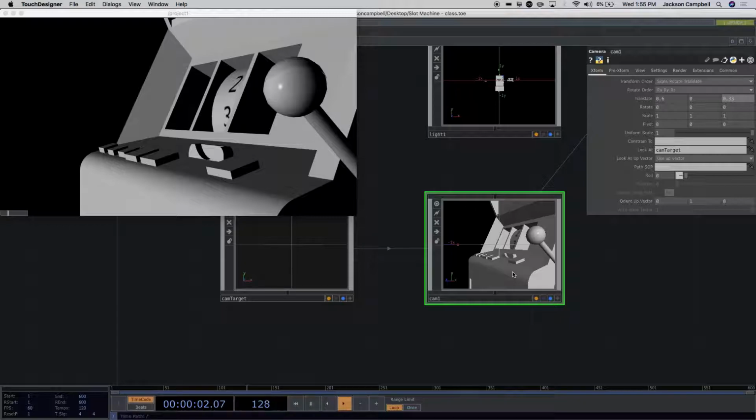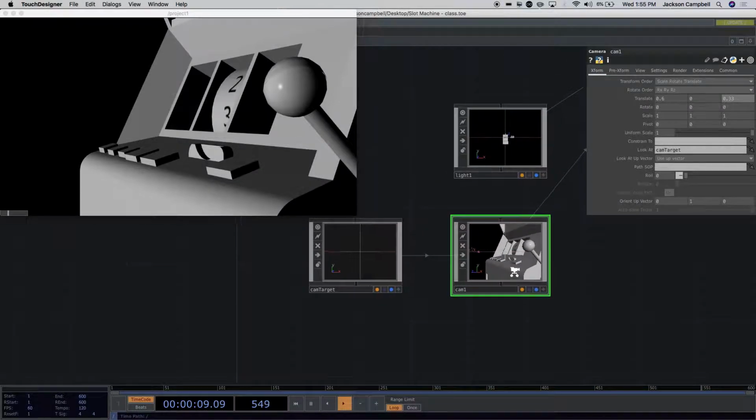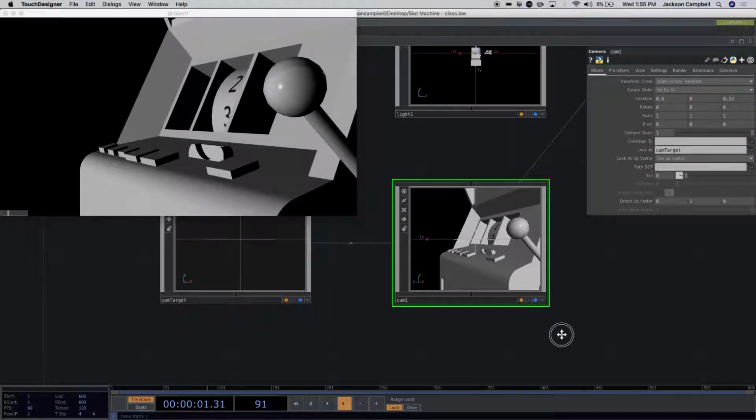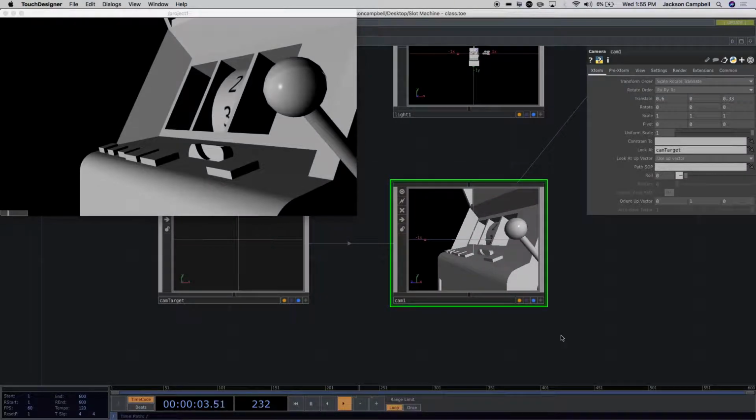All right, so does yours look like this? Does anybody have an issue? Great. All right, so now, yes, you do. What's up? You can't see your wheel at all. Okay, so that's probably just that you have to have the render flag set on your geometry. Go inside of the wheel, and you don't have the render flag set there. The purple one. Got it, great.